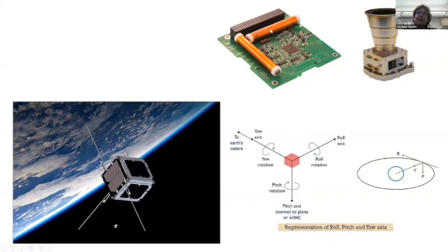These are just electromagnets that are activated or deactivated in some intentional sequence to interact with Earth's magnetic field in a low Earth orbit altitude range to basically self-impart torques on your spacecraft and to control your own pointing, to steer your spacecraft.